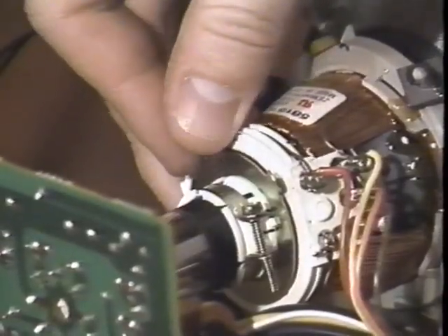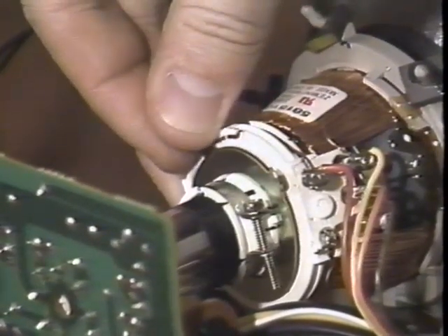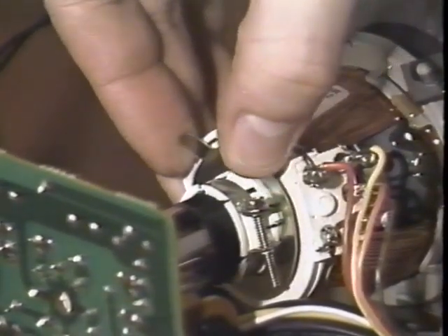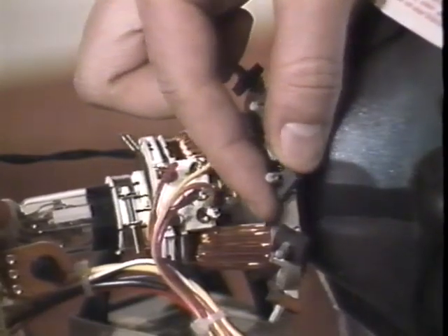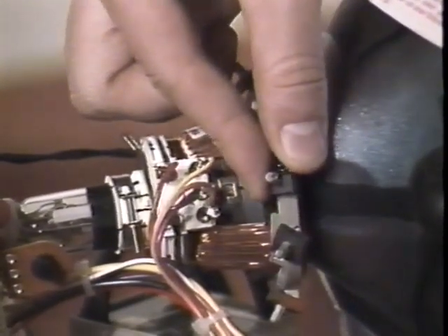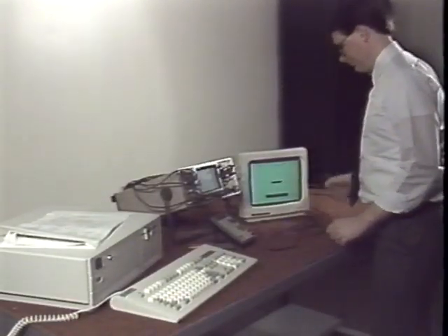Next, center the display area on the face of the CRT by moving the centering magnets on the yoke housing in relation to one another or rotating both of them around the neck of the tube. These magnets will deflect the electron beam slightly, causing the display to move around on the face of the CRT. Finally, check the screen for any pin cushioning or dipping inwards on the sides, and for barreling or bulging outwards. If either of these conditions exists, rotate the raster geometry magnets until the display area is exactly rectangular. This completes the alignment procedures for a monochrome monitor.